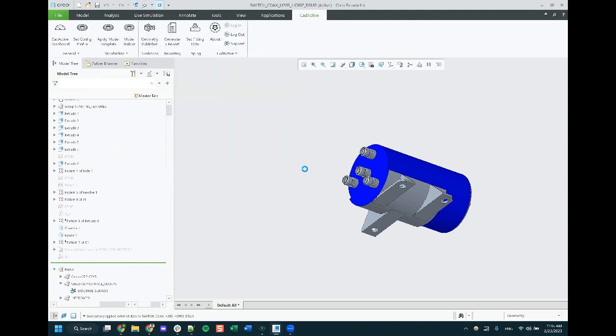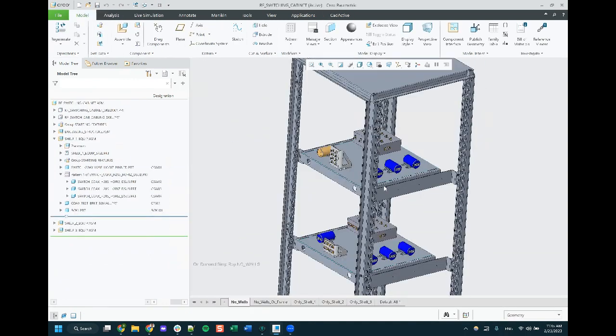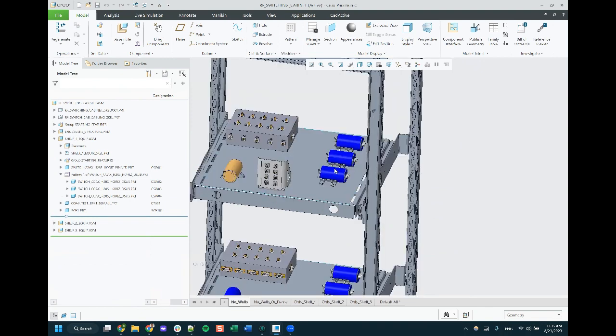So now that we have our library part set up, we can come back to our assembly and start to talk about designations, right? As Phil had mentioned, designations are a way to uniquely identify which component is which. So here we have 3 of the exact same switch model. How do we identify which one of those is which? Because they have the exact same part name. Well, we do it with a designation. We have C switch 02, C switch 03, C switch 04. That way we can uniquely say, this is the specific instance that I'm talking about.